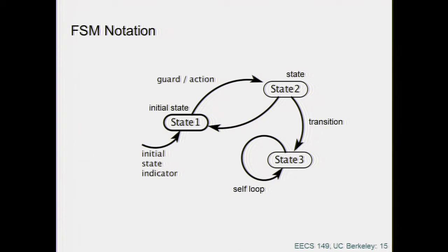Now, there is sometimes graphical notation to tell you what is the state 0, the initial state. And in general, it is a double line, right? So if you have a circle, you have double circle. If you have an oval, you have a double oval. And that tells you what the initial state is. Because now we say state 1, state 0, this and that. And so it's easy to say, oh, okay, this is the initial state.